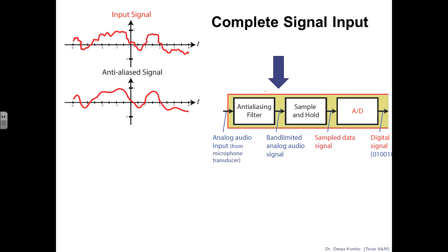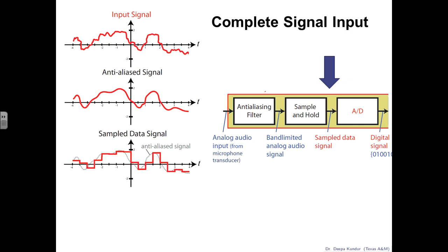Now, it's not unusual to precede an analog to digital converter with a sample and hold circuit. A sample and hold circuit would grab a sample of the signal and hold the value of the output to that one sample, keeping things constant over each sampling interval so that the A to D converter is presented with a constant signal to convert to digital form.